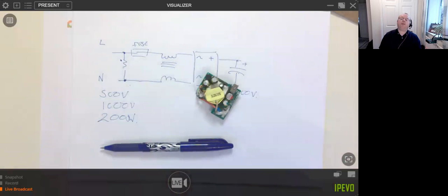As soon as you drop off that peak load current, the efficiency drops. And when the efficiency drops on a power supply, you generally find the emissions will go up. So whatever you buy, you've still got to test it with whatever the end application is.